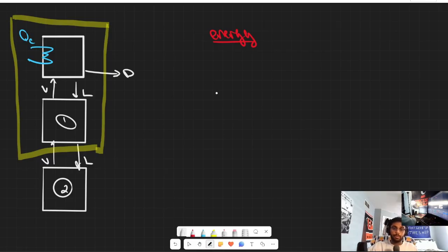That's stuff that we've gone over. So in terms of what is entering, I'm going to say that we have a QC over here. So we have that rate of cooling. And then we're going to have that vapor coming from the stage below. So this is a vapor flow rate coming from the stage below, N plus 1. And then in terms of getting this in energy terms, we want to calculate the enthalpy of that vapor from that stage N plus 1. So these are the things that are entering our system.